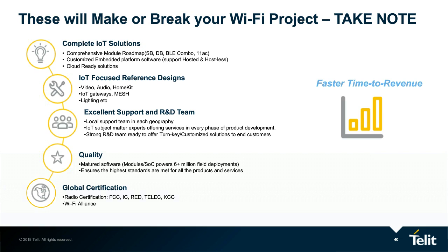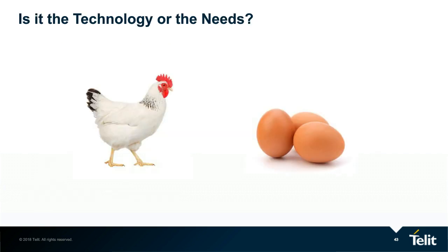The first one that we've received says, you recently announced support for the Lua scripting language for your BT modules. How much resources are available for the script? Florian, would you be able to take that one for us? Yeah, sure. The Lua scripting language is actually quite commonly used in low-end devices, and on our BlueMod S42 module, there is 20K of RAM and 32K of flash available for running the Lua script. So that is plenty of size for a script.